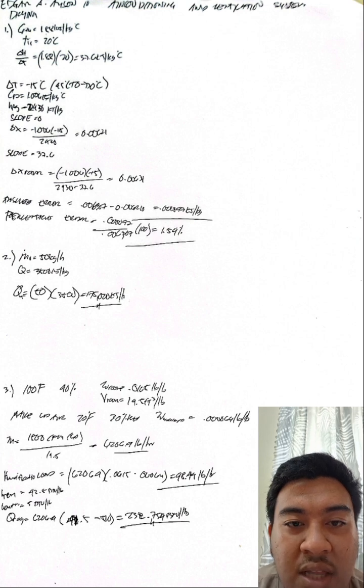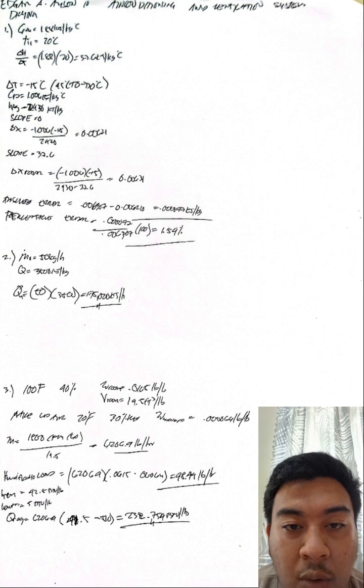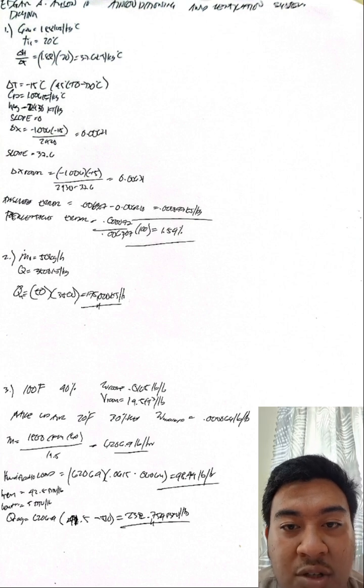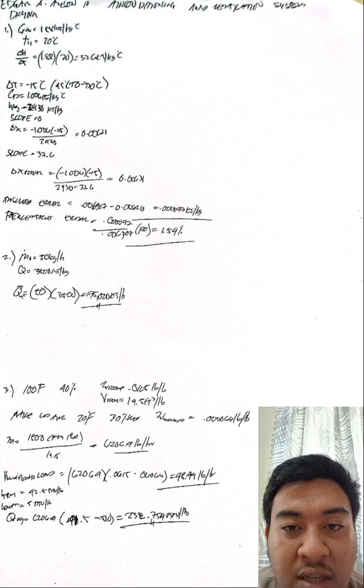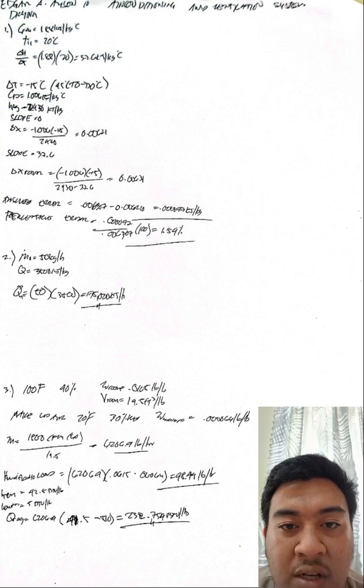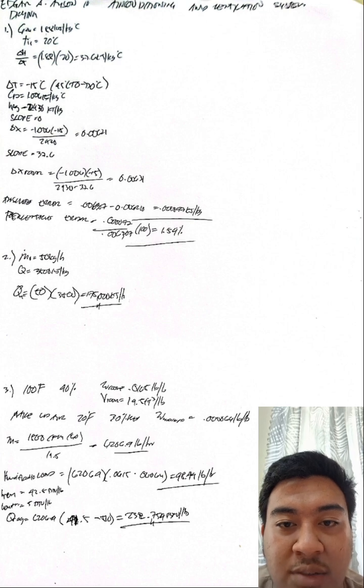So by solving this, the total heat needed per hour is 50 times 3,500, which is equal to 175,000 kilojoules per hour. Then we convert the hour into seconds to get the unit of kilowatts. So 175,000 kilojoules per hour times 1 hour over 3,600 seconds, then the unit hour cancels out, leaving seconds. Kilojoules per second is simply kilowatts. So now our answer is 48.6 kilowatts.